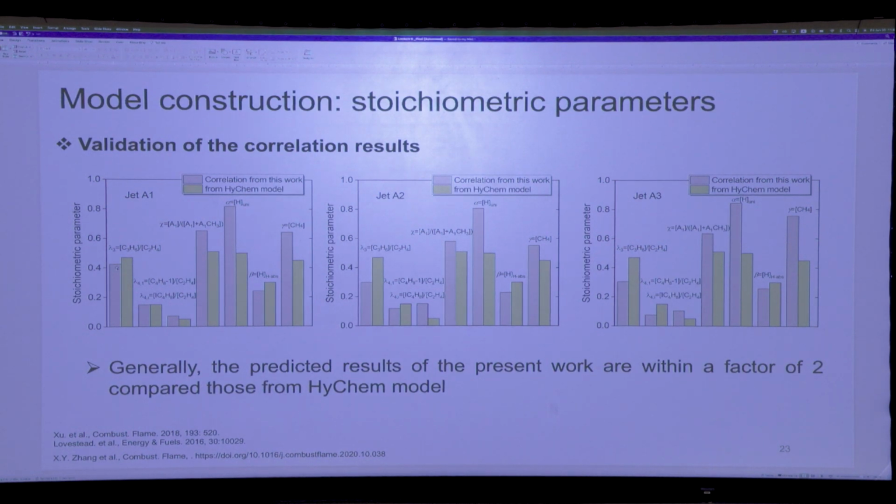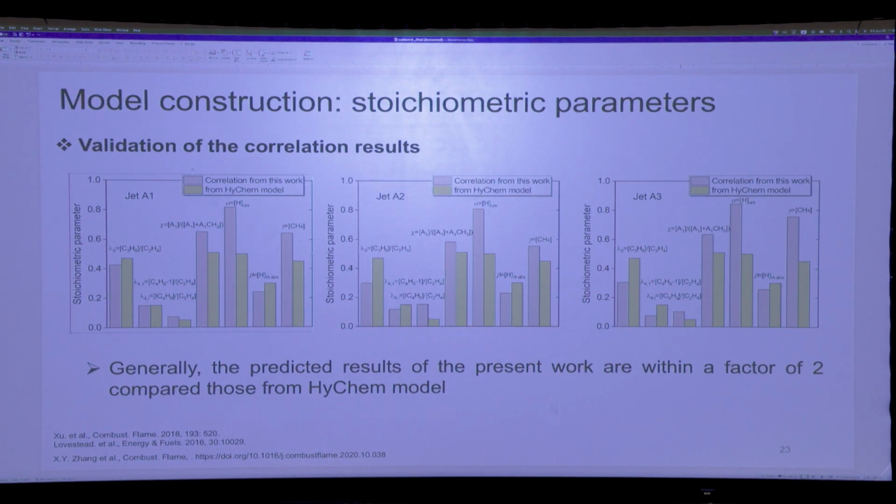So for like lambda 3, lambda 4, the alpha, the beta, the gamma, the chi. Okay, there's some uncertainties. For this Jet A1, we get alpha is off by maybe 40%. There might be 20% difference in the gamma. Similarly, for Jet A2 and Jet A3, we can get within, say, 20 to 40% of the actual values that he got from measurements. And generally, we think within a factor of 2 is reasonable because we'll show even with these errors, you can predict things like the ignition time fairly well.